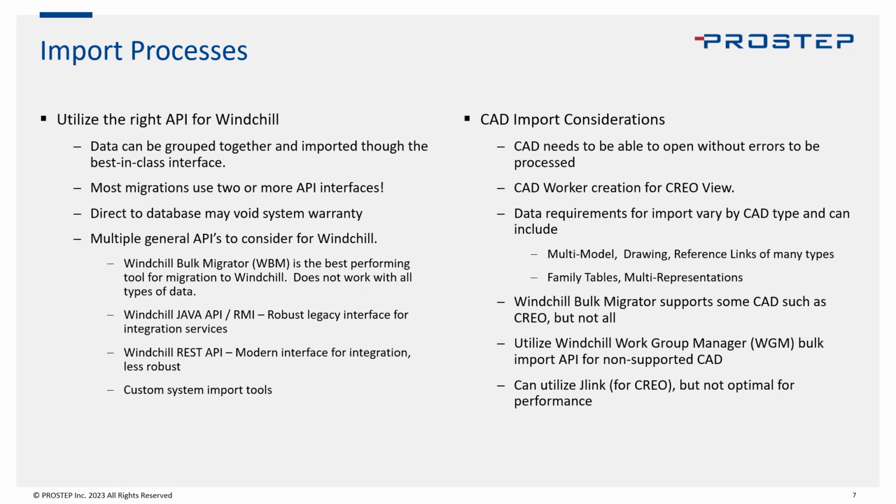Speaking of CAD workers, we need to use those in general for creation of the Creo view. Many times you would populate the data and then queue that up to process it and generate the visualization. But in other instances, you could also create the Creo view on import. That obviously takes longer and it's not as finely tuned, right? So by doing it through a CAD worker, you have the ability to ensure the process is creating the data correctly, which is probably recommended.